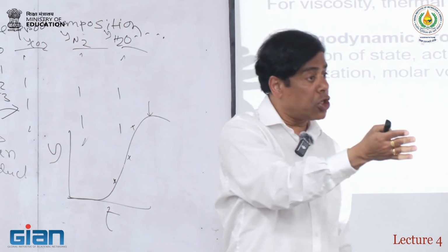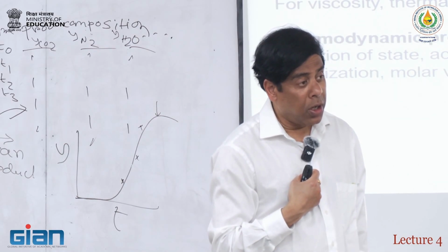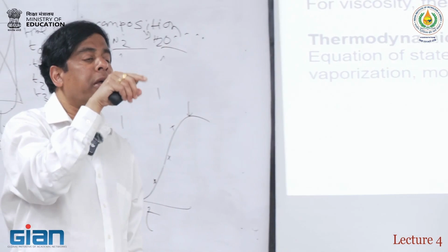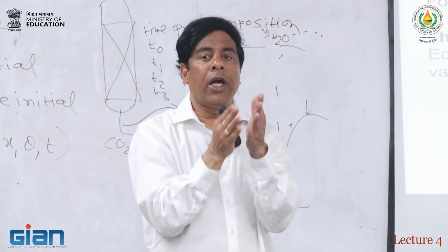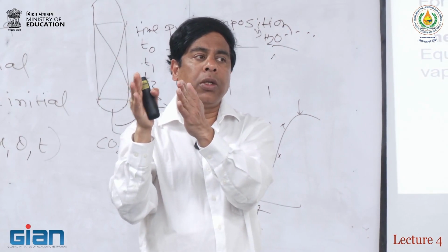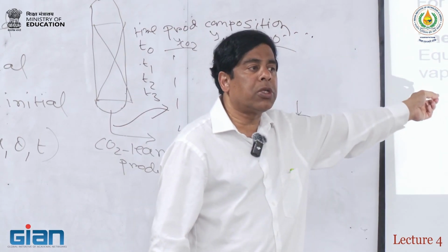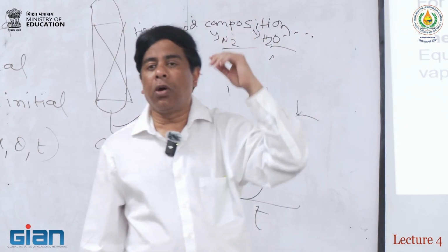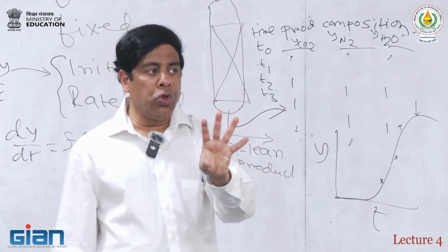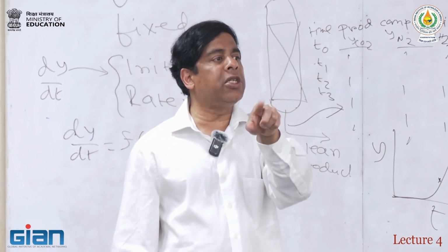We use it for excess enthalpy calculation, remember? Like the delta H excess, when we write the enthalpy model, we write it as an ideal gas, plus we have the non-ideality. How do we calculate the non-ideality? This is all given by the equation of state. So if you are using SRK or the Peng-Robinson or any other equation of state, that's the guy that is used for calculating the delta H excess.